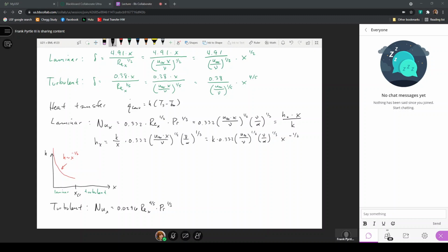That's because in the definition of a heat transfer coefficient, which is a function of fluid properties and geometry and the way that the fluid moves over that surface, well, the Reynolds number embodies the hydrodynamic contribution to the heat transfer coefficient. The Prandtl number embodies the combination of the hydrodynamic and the thermal problem in the definition of that Prandtl number. So we get an expression for the Nusselt number that is a function of the hydrodynamics and the thermal conditions that exist in the problem.